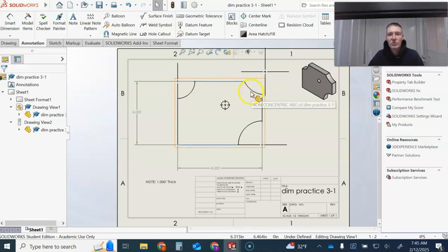Okay, now there are some rules that you probably should follow, but based upon my experiences, I kind of like the arc center because I actually am going to use that. However, I might actually like those points too, and we're going to show you how to put both without over-dimensioning. All right, so let's get to the next thing. We already know where the arc center is here because it's basically at 0 and 6 inches up from the bottom. Okay, arc center is good.